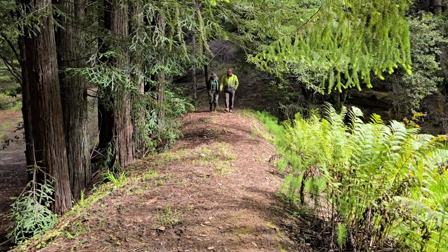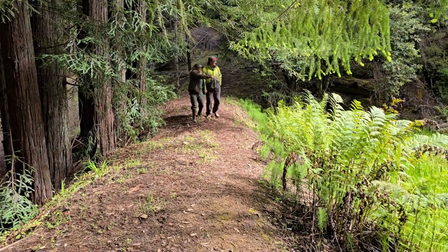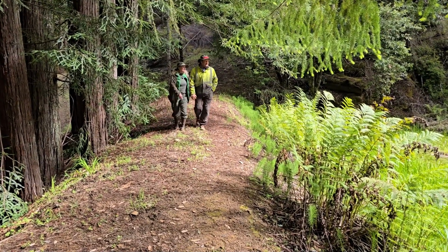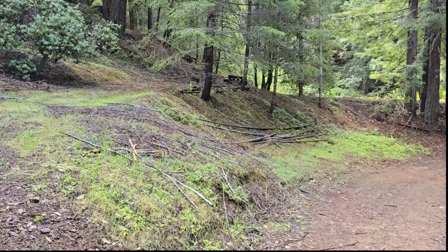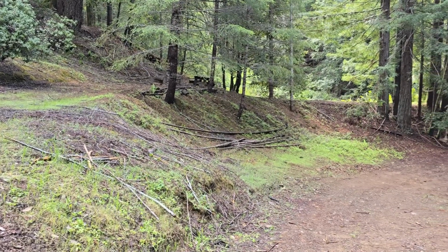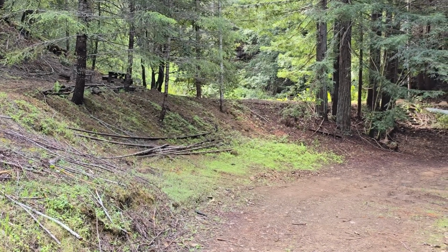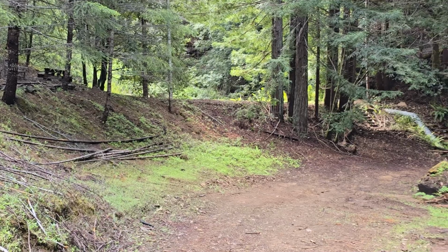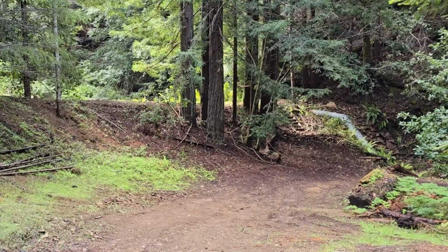The pond on Gabriel's land was constructed over 50 years ago by building a high dam across the stream. The dam was built using clay texture soil that was obtained on site. The dam was built with slopes that were too steep to mow with a tractor. Large redwood trees and Douglas fir trees are growing on the sides of the dam. The roots of these trees are undoubtedly removing large quantities of water from the wetland.